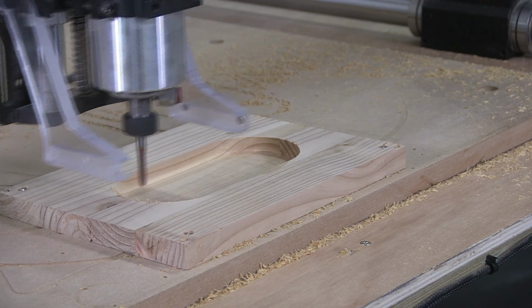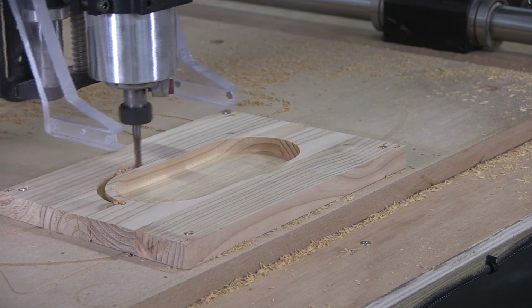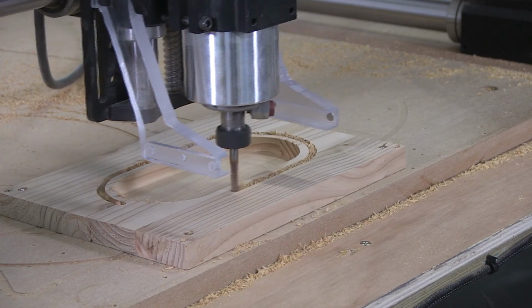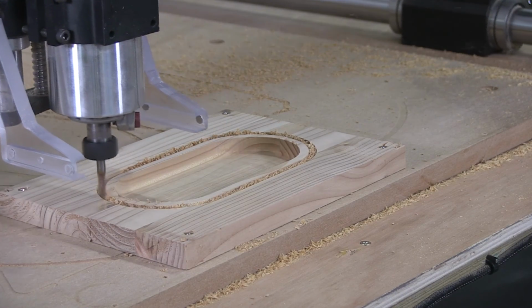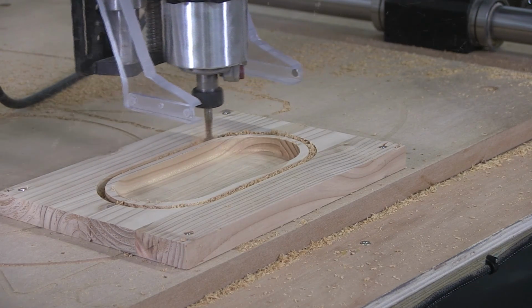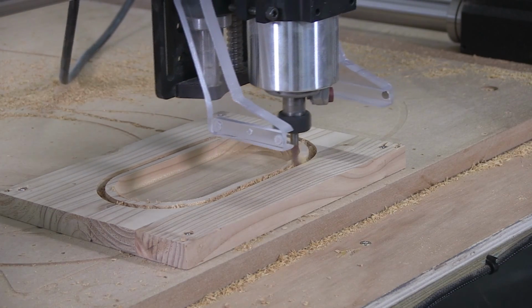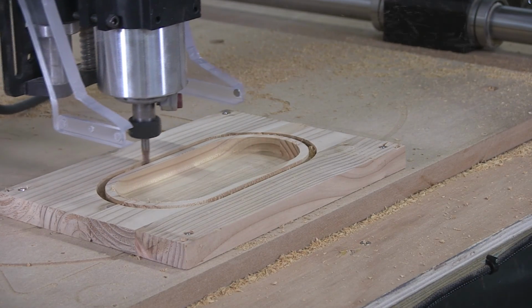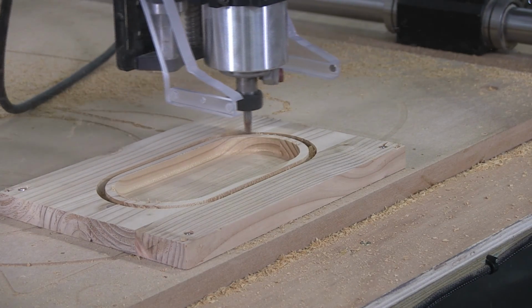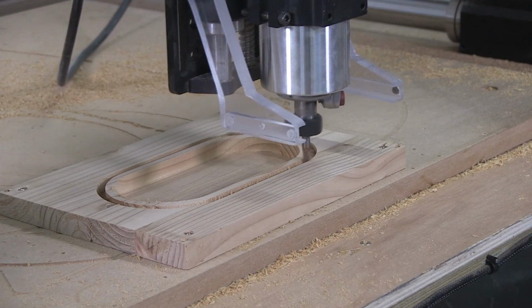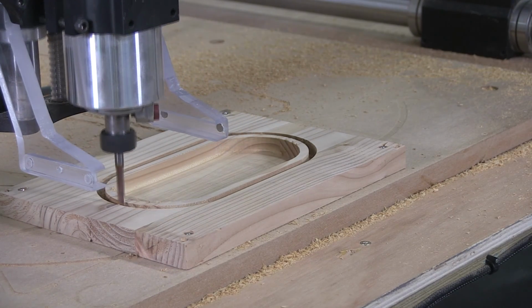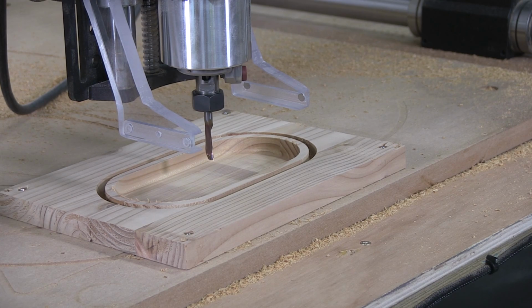So I'll switch tools now and set up my Z for the end mill again. And this is just to cut the part out, so I won't be really that fussed with this as long as it goes through the material. Now, one mistake that I did make was that I forgot to ramp in on this, but luckily it was okay. So it's just jumping up here where I've added those tabs. So that's finished. So I'm going to take the part off now.